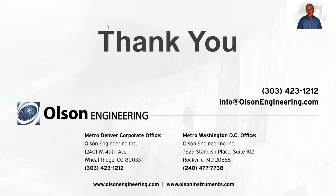We use a lot of solenoids for most of our work, from say nominally 3-inch depths up to 18 inches maybe. And then we start to use the hammers to go to lower frequencies. So as long as you don't violate those things, that's a good general rule of thumb. And maybe we would take 2048 points.